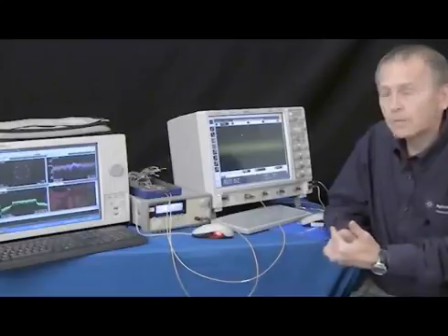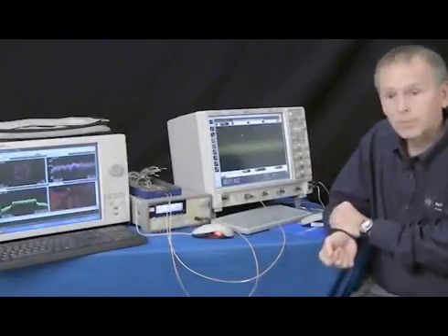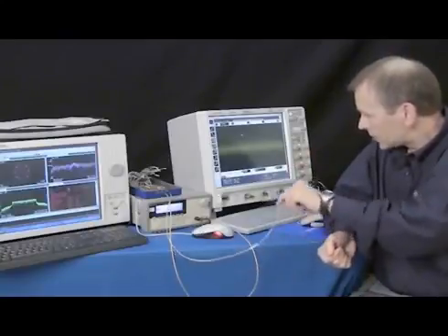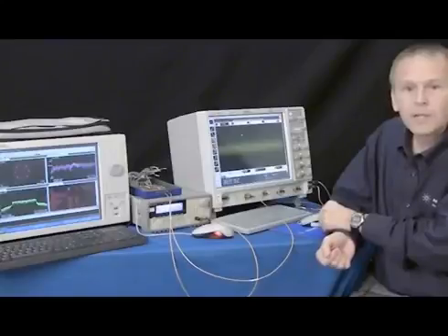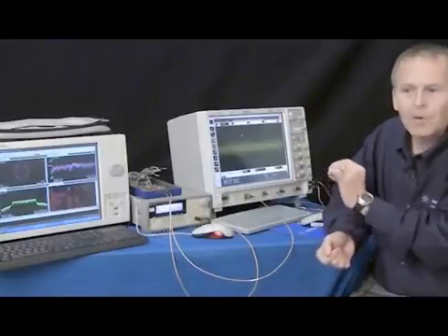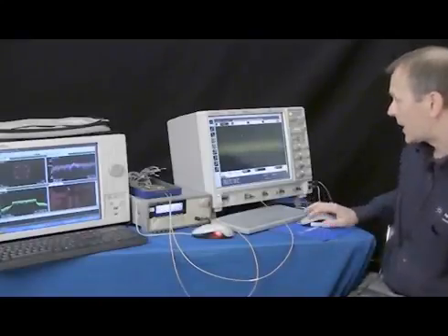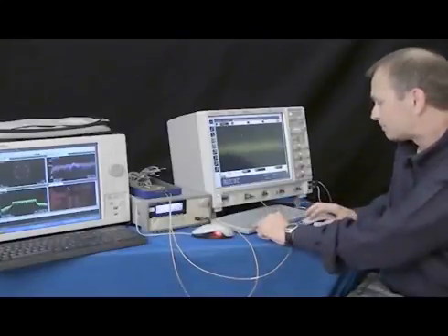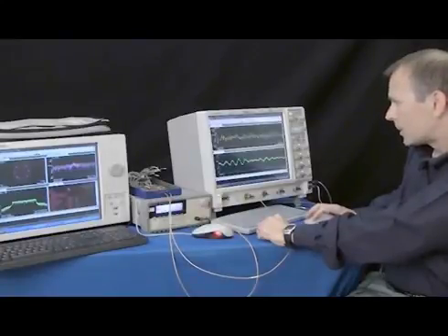Get through the D to A converter, and the way we're going to look at that analog IF is with an oscilloscope. So here is that signal we're bringing in by coax. It looks like an LTE signal, but I need to dive deeper into, is it meeting the specification? For that, we're going to use VSA again. So I can bring up VSA and import the scope signal into it for a final view.